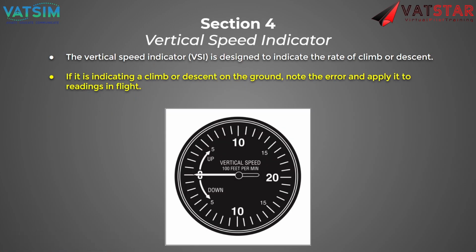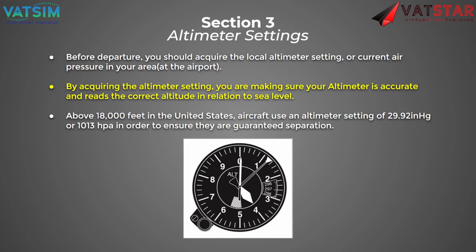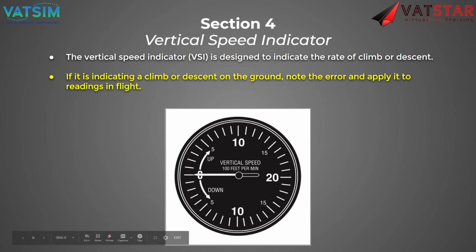Why doesn't the triangle line up on the 4? Which triangle? The big triangle, wouldn't it be on the second hash mark past the 1? It should be. They're not always calibrated perfectly. It's less than 5, so I know it's close enough, but I know that I'm more than 10,000 feet at the very least. So that could be an instrument error, but I know that I'm above 10,000 feet, and I'm at least 4,000 above 10,000, and I'm at an even number, so I know 14,000. Yeah, it seems like you should be able to look at that triangle alone and tell where you are.